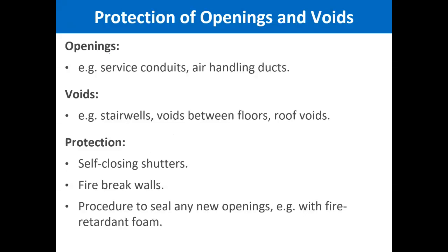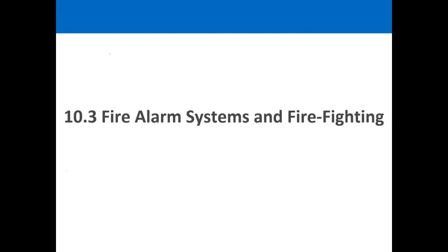Openings and voids, obviously, you need to make sure they're controlled, otherwise fire or heat will spread through them and cause fire as well. Self-closing shutters should be given, fire break walls should be available, and there should be a procedure to seal any new openings with fire retardant foam.